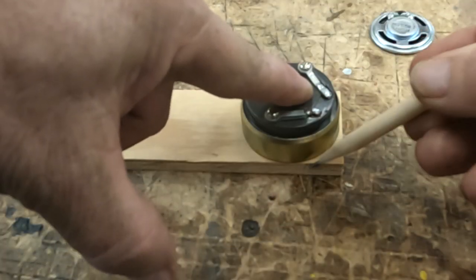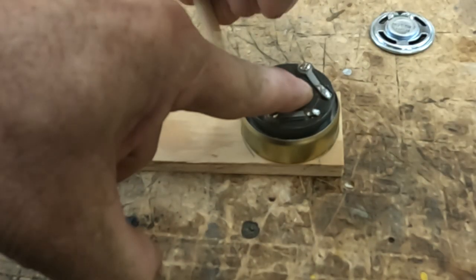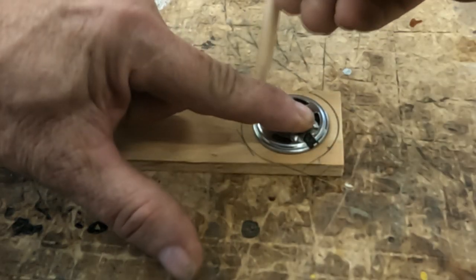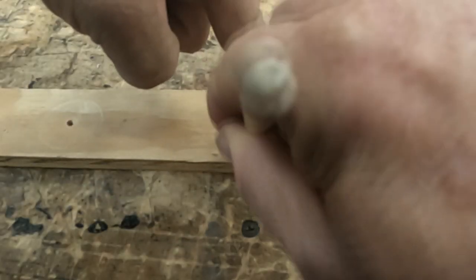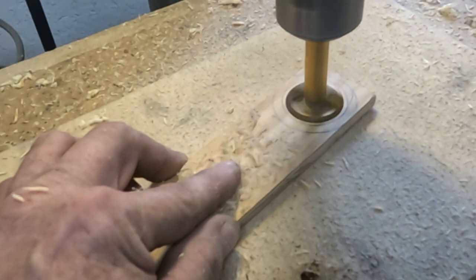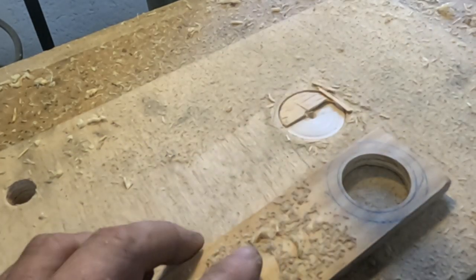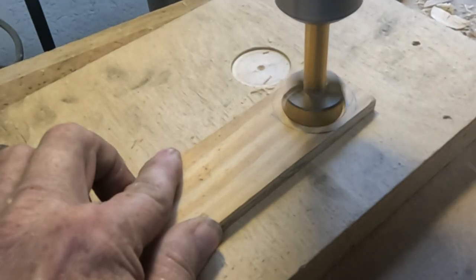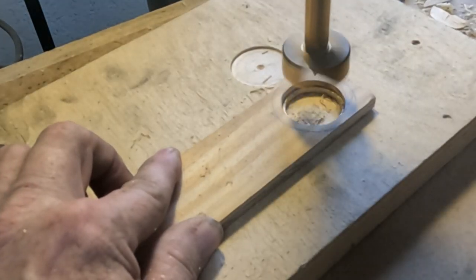With the original speaker removed, make a tracing on a piece of 3/8" plywood. Then place the included sound module speaker in the middle and trace it as well. You will need to drill out the hole in 2 steps. First, make a 1 1/8" hole all the way through. Then make a 1 3/8" outer hole about 2/3 of the depth inside. Thus it is now a 2-step hole.